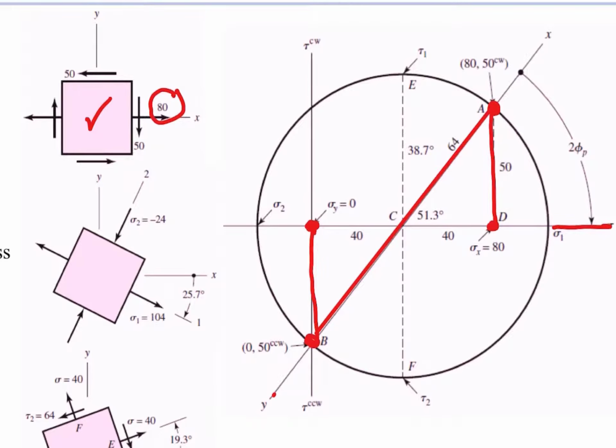So now what we can do is rotate in Mohr's space by twice some angle. If we rotate twice phi, what we identify is the principal stresses, meaning no shear stresses. We identify an orientation of the volume element, which is shown here on the left, where all we have is normal stresses acting on the faces, no shear stresses. This is called a principal stress state and a principal stress orientation for the particular volume.